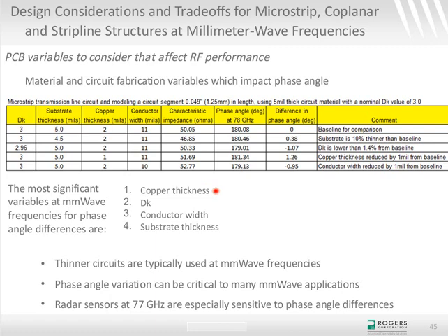That's the copper thickness, as we make the laminate, the raw copper itself, and also the circuit fabrication that does plate out copper on top of our copper, and that variation is something you probably should be pretty mindful of. As you can see, that's the top dog here. That's the most important. Next in line is dielectric constant variation. So here, dielectric constant variation is a big deal. Having a material that's tightly controlled is really important.